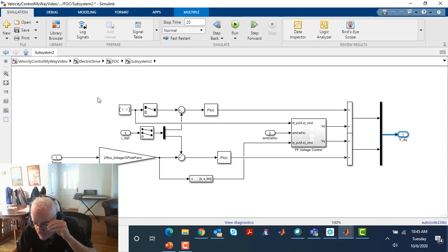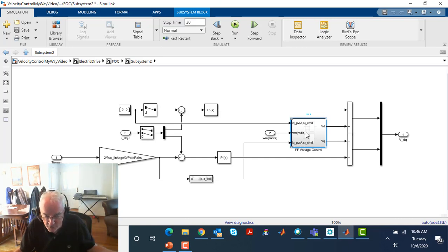And so with regard to this, we do want our direct current to be 0, and we set that right here, right? I'll explain why I'm having a 2-component right here that's used by this term probably in a separate video, because it's a really cool idea, but it would take another 10-minute venture to explain. But I will point out that here are some PI loops employing feedback and driving our direct current to 0. And here's a PI loop on the quadrature, and you'll see that the quadrature command on current is going to be fed by torque.